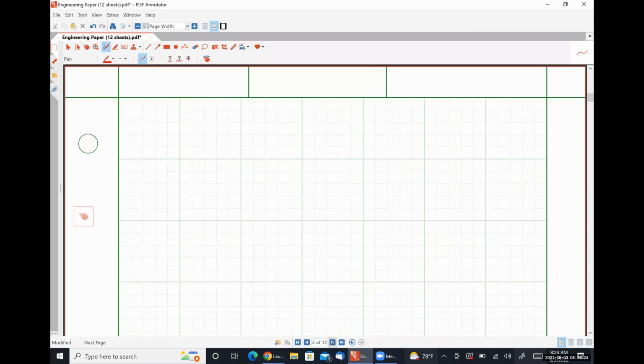So we can use this result to observe a few things. Our neutral conductor current, INN, is negative VNN over ZN, and this has to be 0. Okay. I'm going to write something out here.